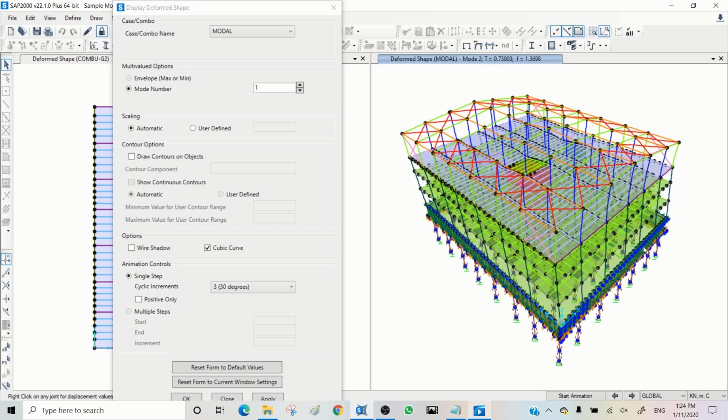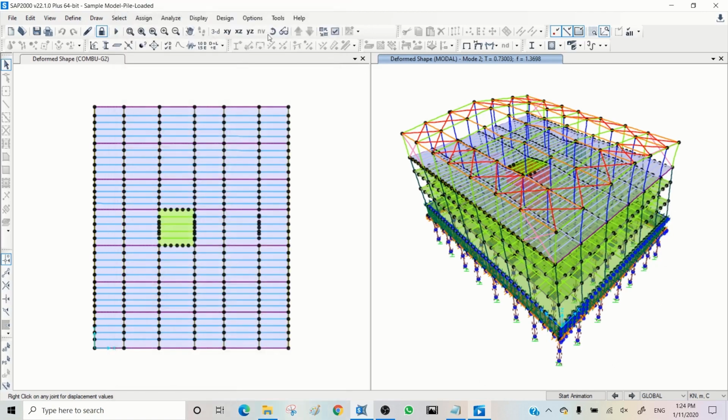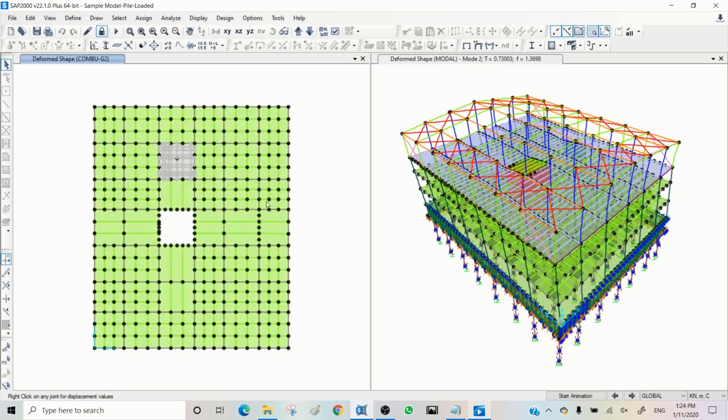But if you remember, we have a few other walls, and let me show you here, you remember probably the walls are all along Y direction. So Y direction is stiffer than X direction. That's why X comes first. Okay, so looks like we don't have any issue, but let's move on and figure out how we can find errors.